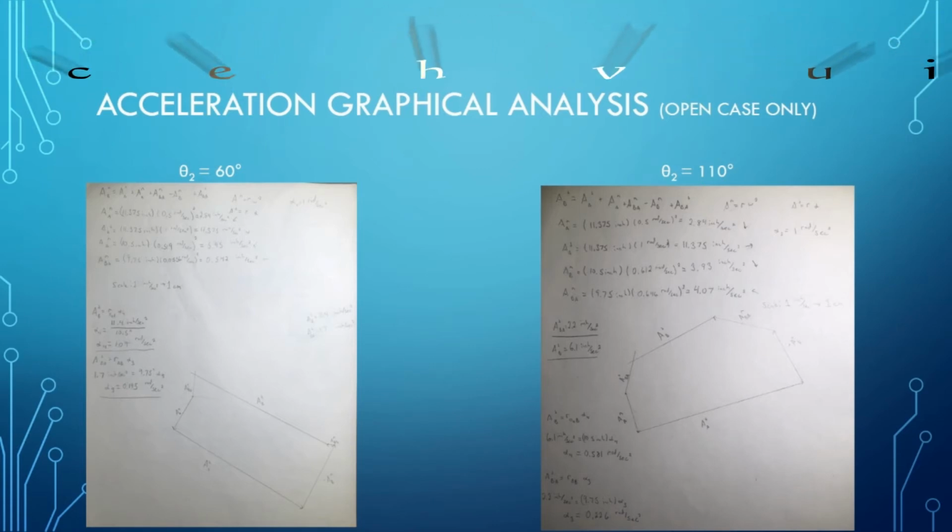We followed on from before, where we used the theta 2 value of 60 degrees for the first example, and we ended up finding alpha 3 value of 0.195 radians per second squared and an alpha 4 value of 1.09 radians per second squared. And then our second case, we used theta 2 equals 110 degrees, and we found an alpha 3 value of 0.226 radians per second squared and an alpha 4 of 0.581 radians per second squared.